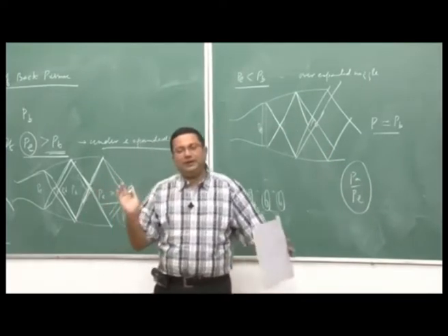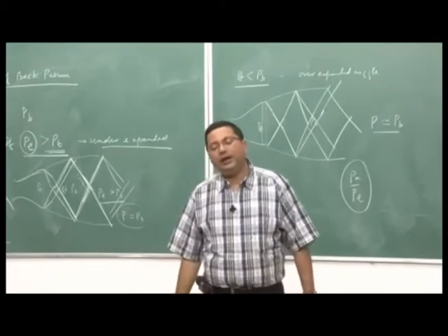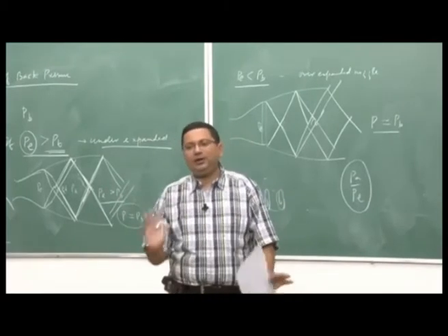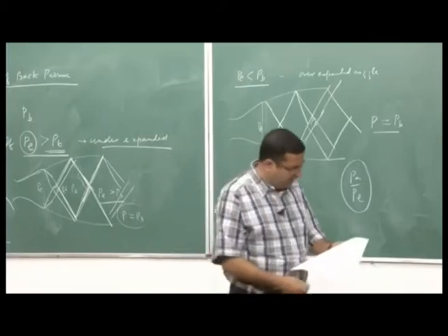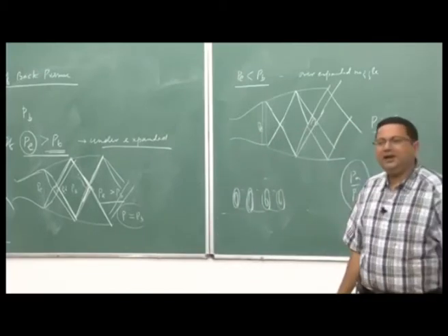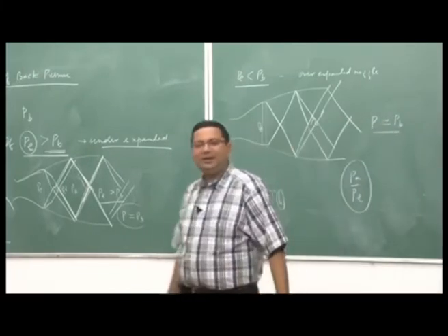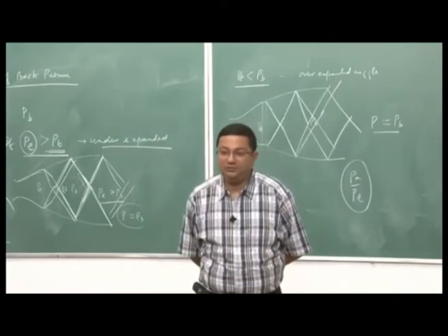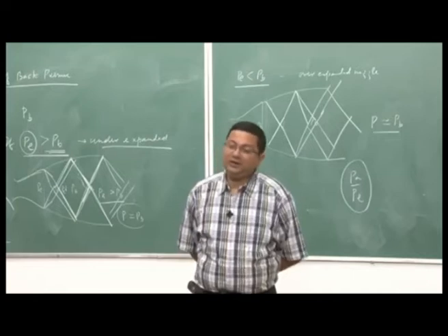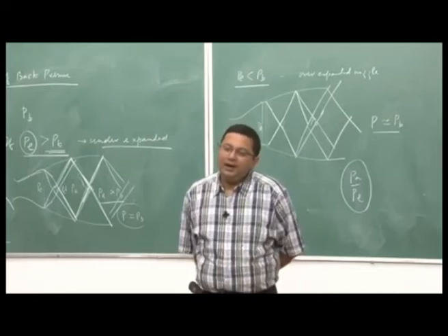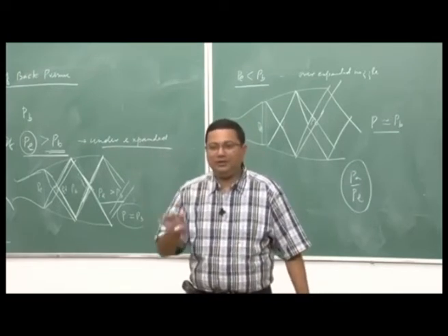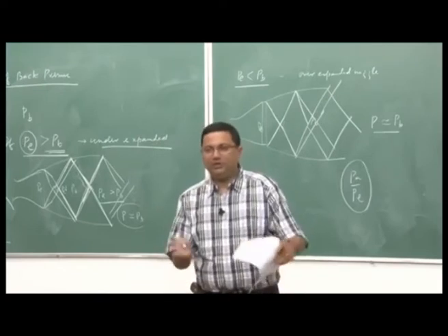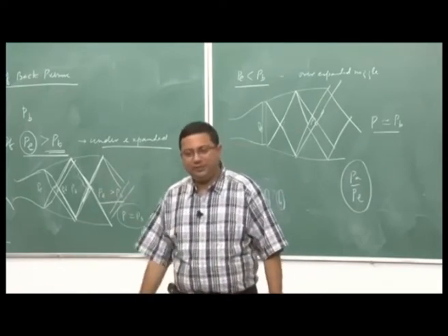There is a passive way in the design stage itself, we can make sure that we get an optimum condition. But are there any other ways? Yes, what we can do is we can have a variable area nozzle, right. So, we can change the exit area and we can play with the variation in pressure. So, the area keeps on changing, we can maintain the pressure.